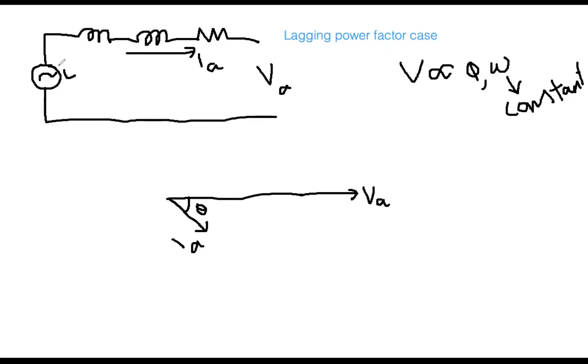This was the internal voltage, EA. The air gap voltage was here, E phi. And this was my RA, armature resistance. This one was the leakage reactance, XA, and this one was XAR. A few minutes ago we discussed this. So this diagram will help you draw the phasor diagram for the lagging power factor case.